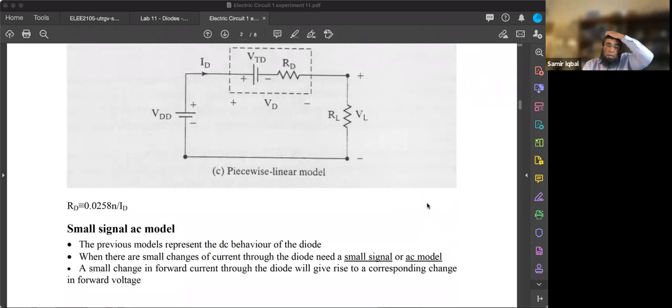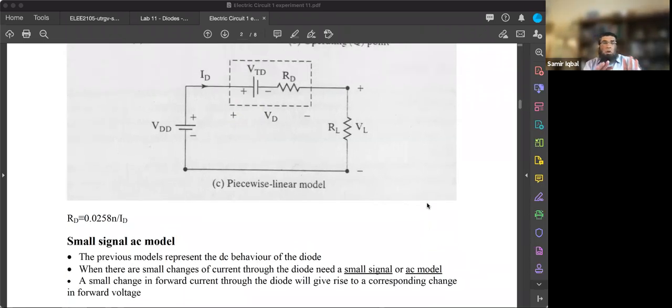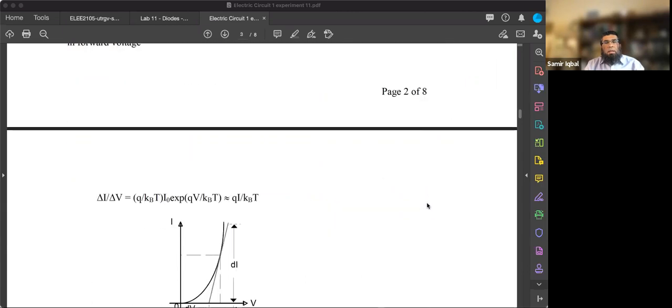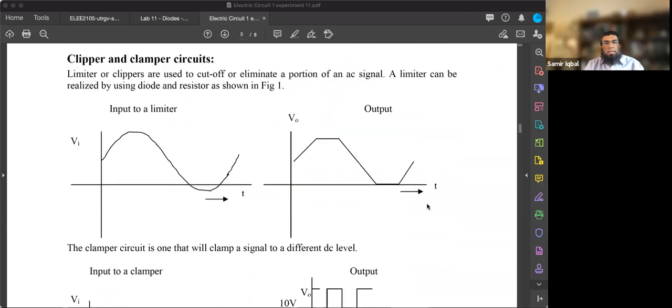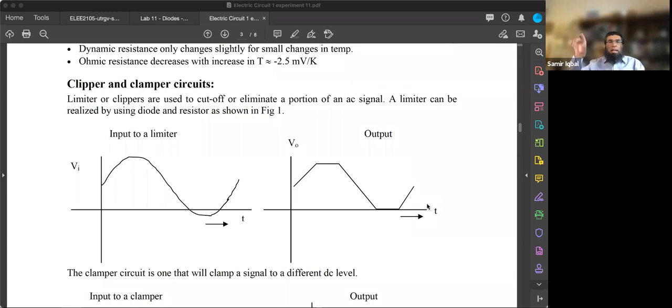All right, so, but now this was for DC, all good. Forward bias, short circuit, reverse bias, no current. But if you keep on cranking, then breakdown, right? Now, for alternating current. Alternating current is nothing but a current that's continuously changing direction, right? So it's going positive, it's going negative, which means in the positive cycle, the diode would be forward biased. It would be conducting current. In reverse bias, it will not be conducting, all right?